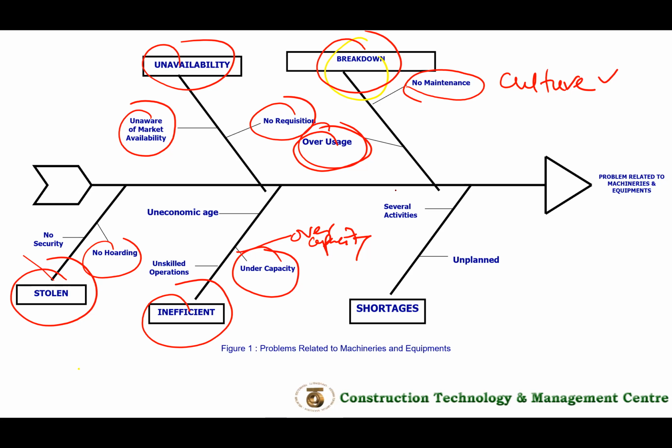And then unskilled operation. All the machinery is normally managed or operated by a so-called operator, crane operator, everything we call an operator. Sometimes we can purchase or rent big machinery, but then the issue is who is going to operate those things. The bigger the crane, for instance, the more skillful the operator has to be. There might not be people who have a license for a 300-ton crane or even bigger. Only a few people around. So you must think about those issues.